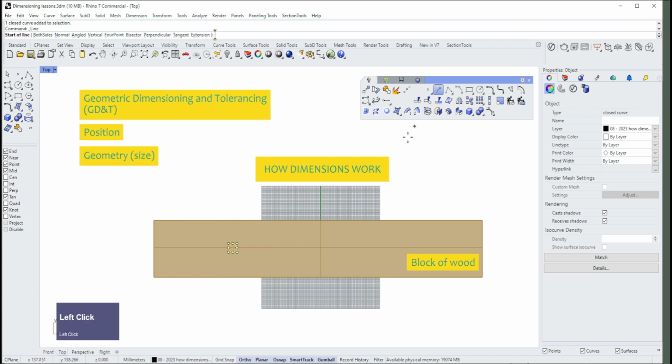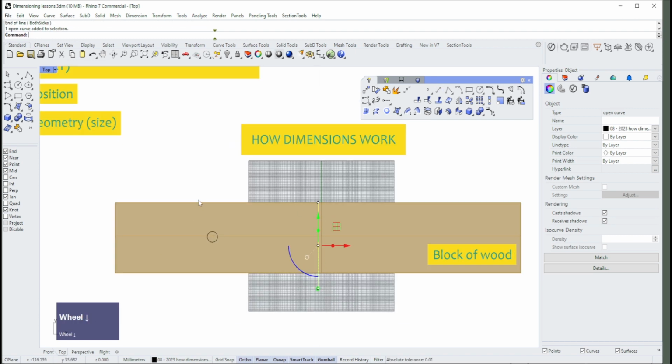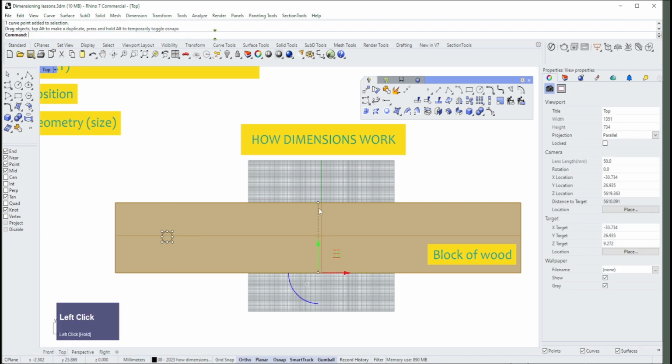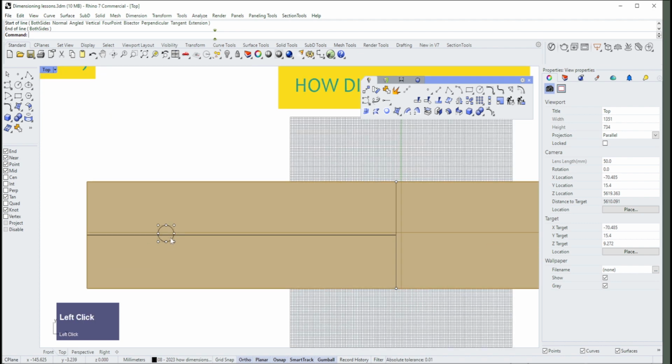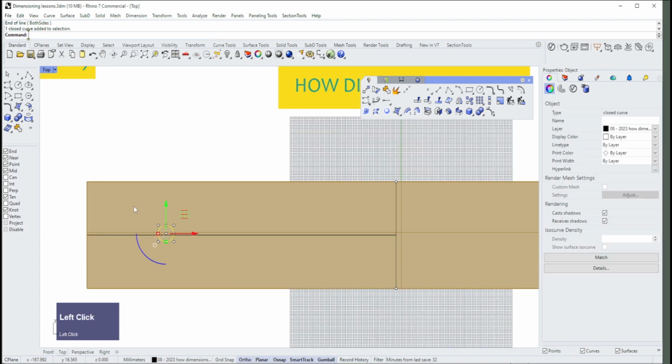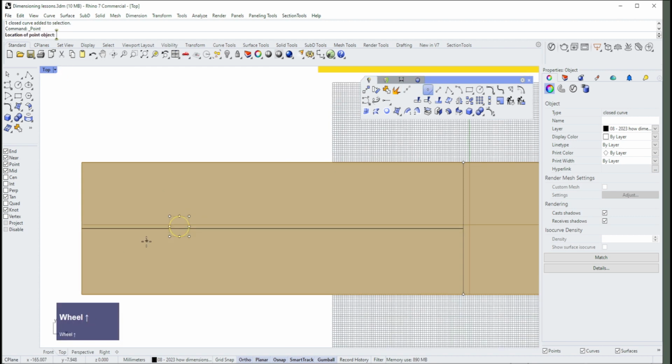So I'm going to assume that we're going to measure from the middle, right? So I'm going to go middle down like this, and that's going to be my measuring point. So I would measure this block of wood, and it would be 390, and I'd divide that by 2 to get 195. And then let's say I want this piece here to be a certain distance from there. So I would draw a line across, and then I would draw perhaps another center line, one going all the way across like that. And then I would locate my point. Obviously it wouldn't be a circle, it would just be a point. So let's put a point in here.